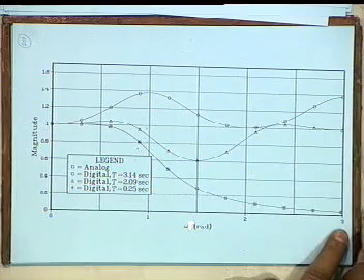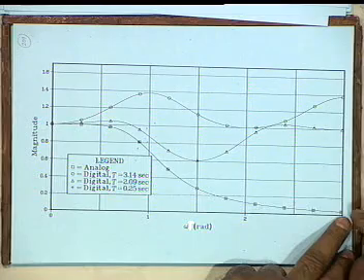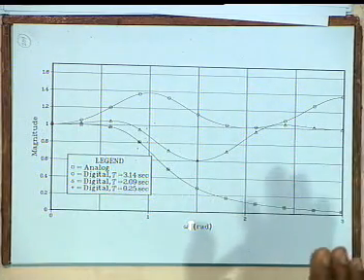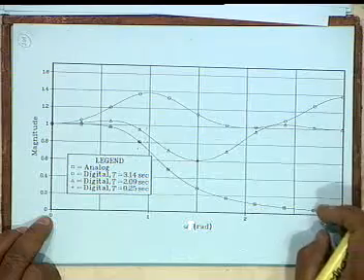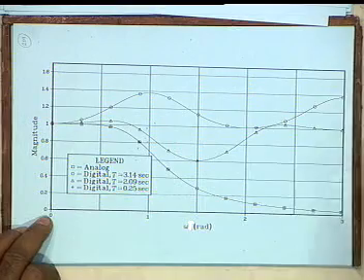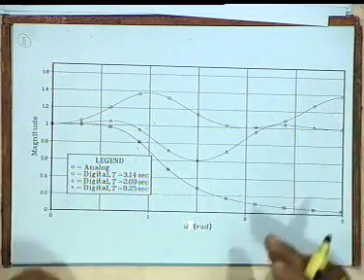Of course, if you continue this, you see what is the value here, 3. If you continue beyond pi, then the analog filter and the digital filter will differ considerably. What will happen beyond pi? This will rise, is that right? Our digital filter frequency response, we are happy to be confined to the baseband. If we go beyond 3.14, obviously it would rise like this because it's periodic. We are not concerned about that. We are concerned with the match only in the baseband. Okay, we will stop here for the